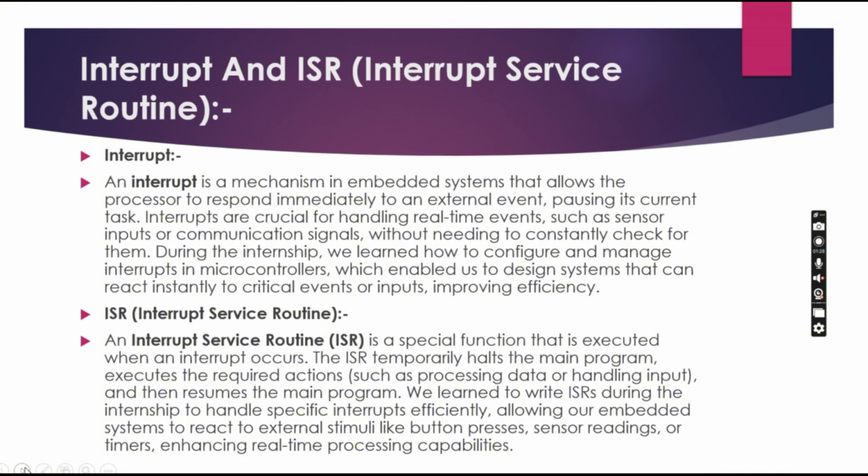ISR, Interrupt Service Routine. An interrupt service routine is a special function that is executed when an interrupt occurs. The ISR temporarily halts the main program, executes the required action, such as processing data or handling input, and then resumes the main program. We have learned to write the ISR during the internship to handle specific interrupts efficiently, allowing our embedded system to react to external stimuli like button presses, sensor readings, or timers, enhancing real time processing capabilities.